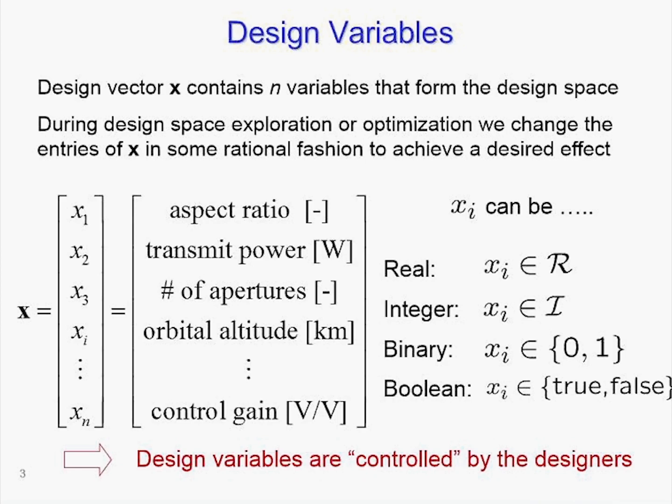What are things that could be parameters? Material properties could be parameters. Sometimes speed is actually a parameter. Often aircraft are designed with speed being fixed and not something that you can vary, so often Mach number might show up as a parameter. Anything that's going to go in the problem that's going to affect the constraints or affect the objectives, but is not going to be allowed to vary.